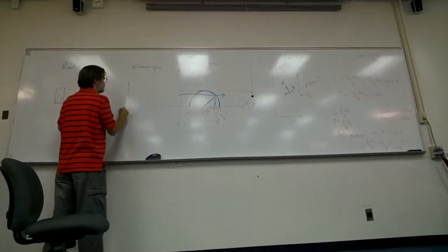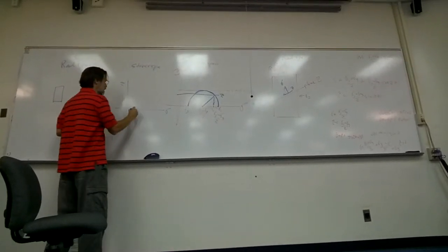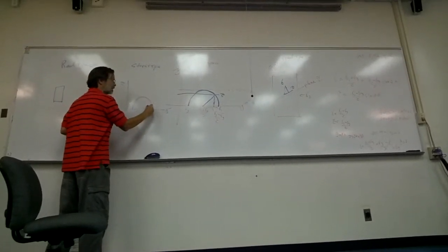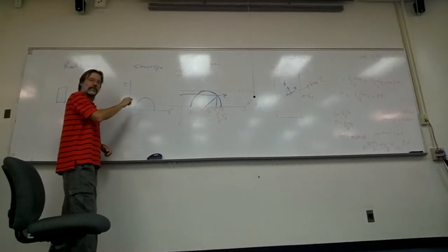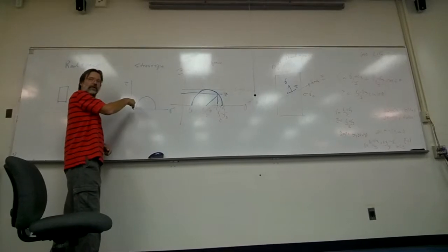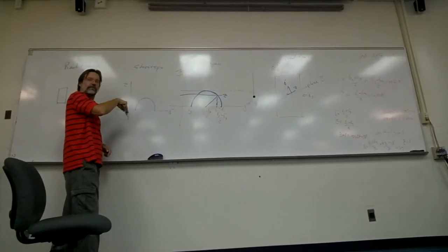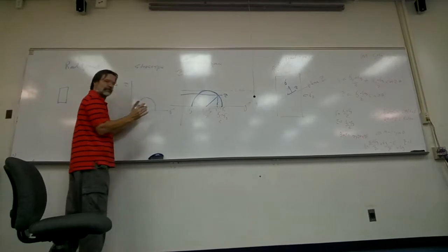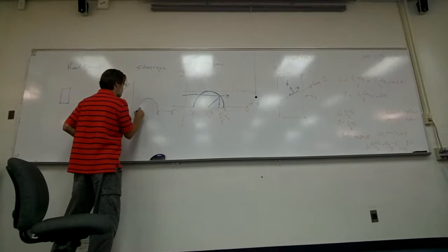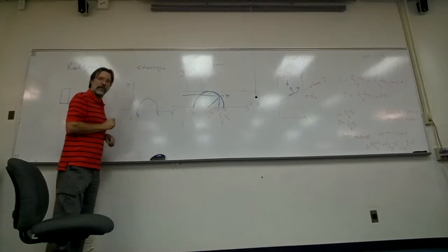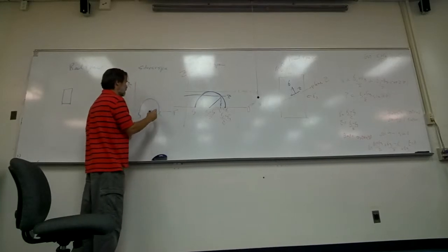So if we redraw this figure, sigma, tau, and there's a Mohr circle here. I'm going to show half of it because the other half is redundant. Once I get to here, I've already gone through 180, which is 360, so I only have to deal with half of it at the moment. There's a sign problem, but this value is sigma 1 and that's sigma 3. Fair enough? The way we set it up here, right?